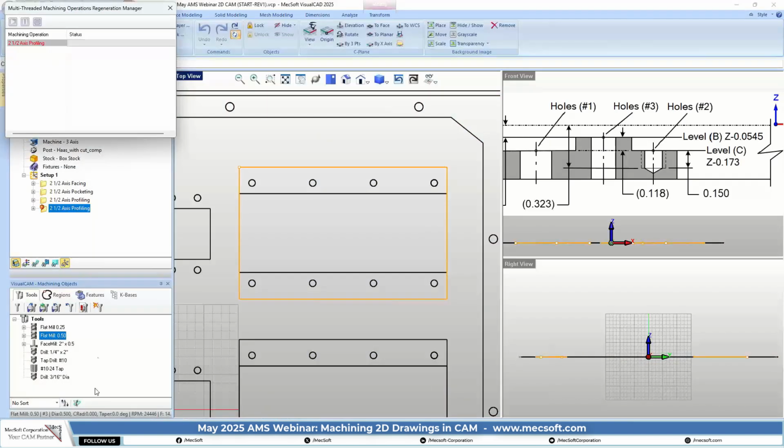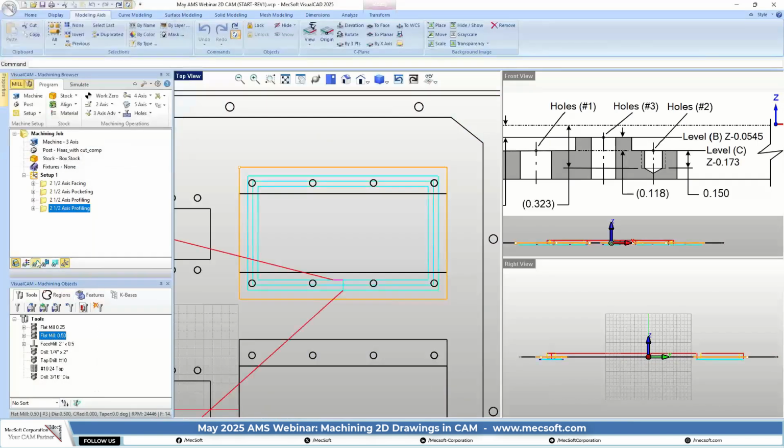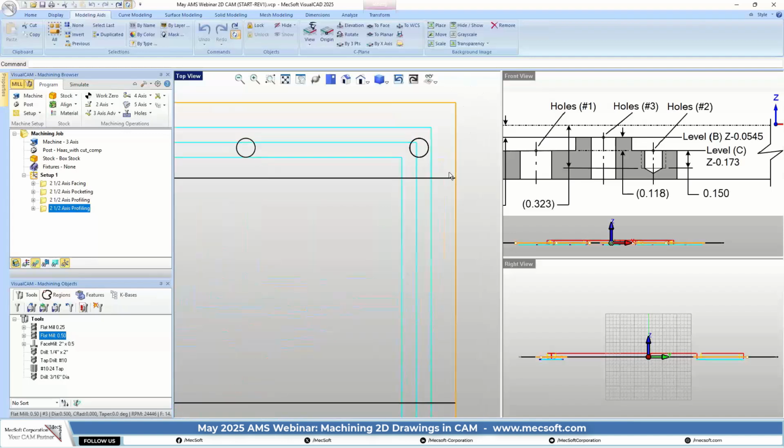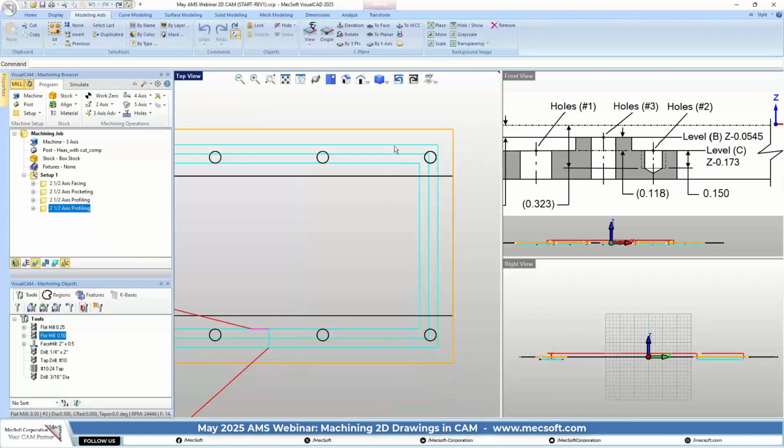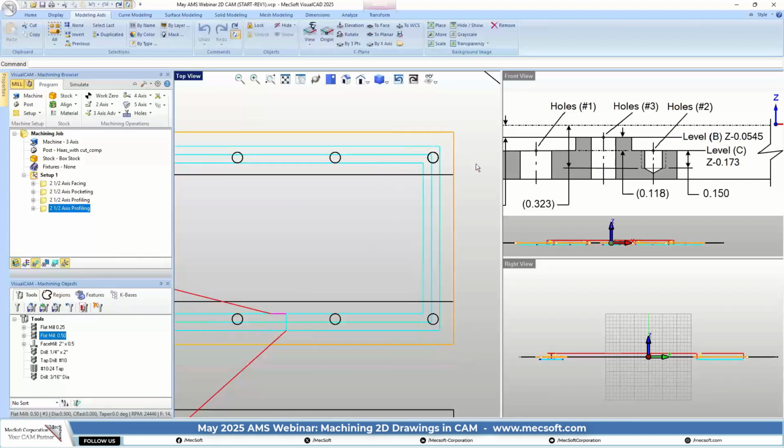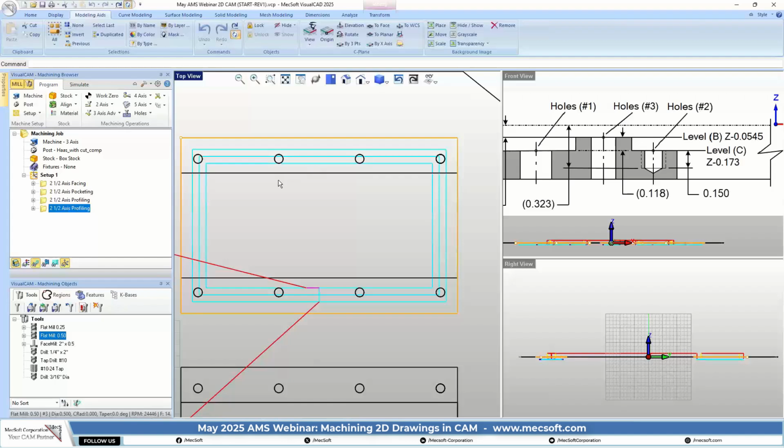Let's generate this. Turn that on. Okay, so you'll see what happened is it created 3 not cut levels, but 3 step overs. Okay, so the first step level cleared it past this cutout right here, and then the last one is the finishing path. Now you might be asking, well, you're cutting air right here, because this already goes all the way through.